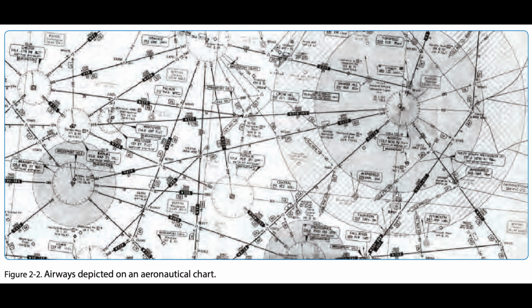Airways have names consisting of one or more letters followed by one or more digits, e.g. V484 or UA419. The en route airspace structure of the National Airspace System, NAS, consists of 3 strata. The first stratum, low-altitude airways in the United States, can be navigated using navaids, have names that start with the letter V, and are called Victor Airways.